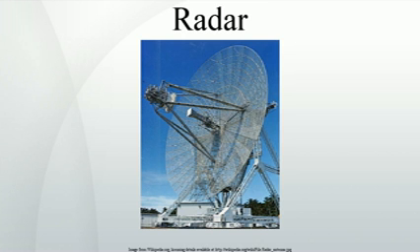The maximum range of a conventional radar can be limited by a number of factors. Line of sight, which depends on height above ground. This means without a direct line of sight the path of the beam is blocked. The maximum non-ambiguous range, which is determined by the pulse repetition frequency. The maximum non-ambiguous range is the distance the pulse could travel and return before the next pulse is emitted.